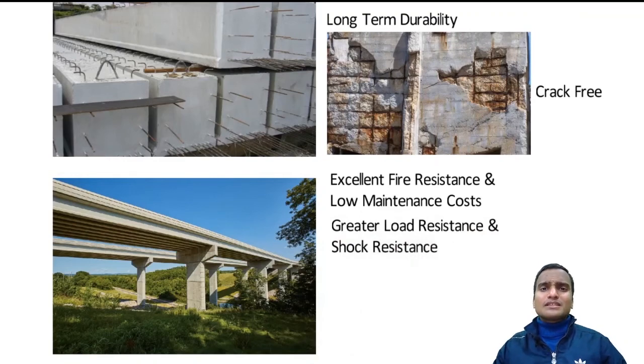Now, what is the maintenance in pre-stressed concrete? One maintenance is very important. Maybe after a certain interval of time, the stress that we have imparted in the tendons may reduce with time because of loading, certain repeated loading. So we may have to tighten the tendons again at the jacks, so that the tendons restore their initial force conditions. Okay, so that maintenance is very important, and that is usually done in all those bridges at a certain interval of time. They also have greater load resistance as well as shock resistance.